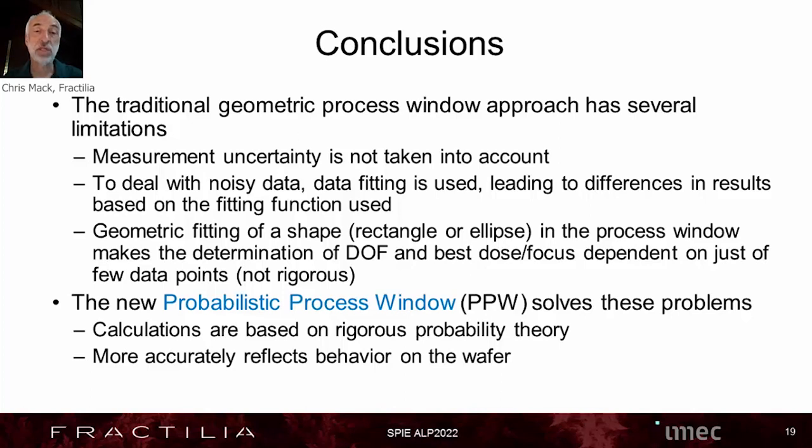But the new probabilistic process window solves all of these problems based on a rigorous probability theory, taking measurement uncertainty into account, and more accurately reflects behavior on the wafer. So I'm quite confident that the probabilistic process window approach will become the new standard for how to measure, analyze, and use process window data for focus exposure matrices or others, because this approach is not, in fact, just limited to focus and exposure.